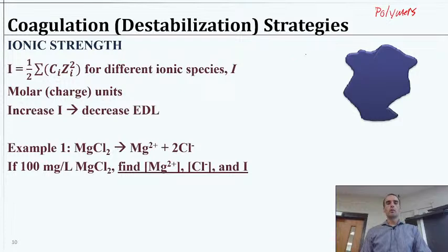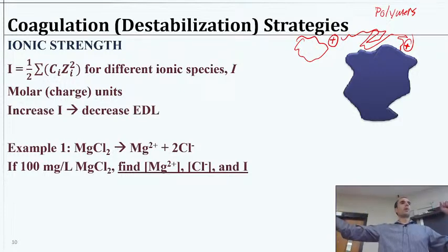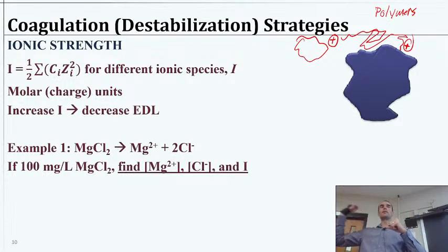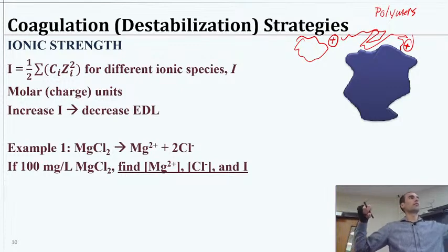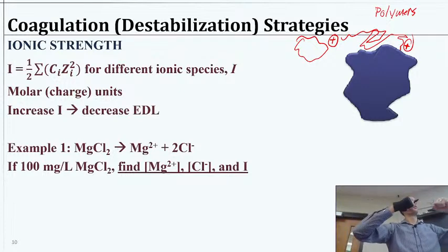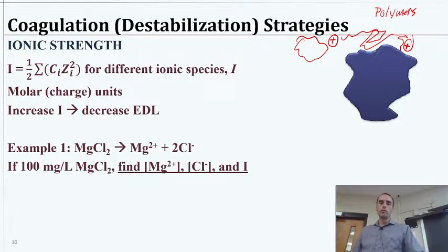this is just a fancy word to say, well, if you have two different particles, and you have some polymer that maybe has some charges on it, and who knows what shape that polymer takes, but if it has a couple charges or a couple spots where it likes to interact with these particles, it's sticky to them, and has a good chance of reaching them and connecting to them, then they could potentially bridge the particles and grab one with this hand and grab one with the tail or whatever, and now these particles are attached and ultimately going to stick together. So there are polymer aids as a tangent, another way of causing particles to stick together.